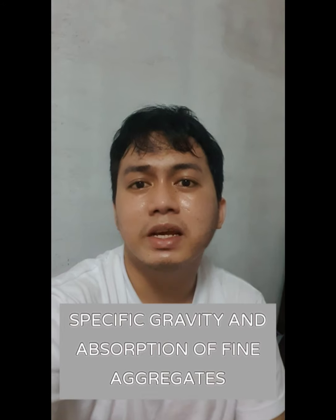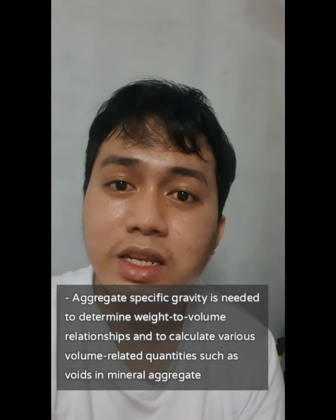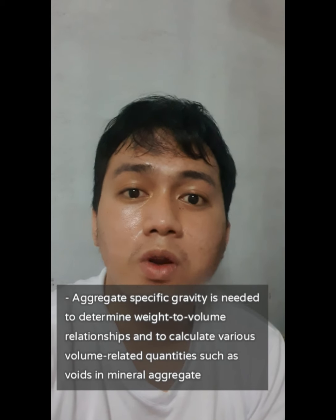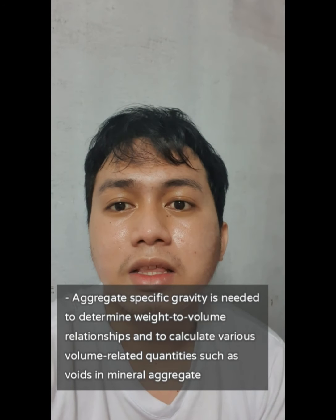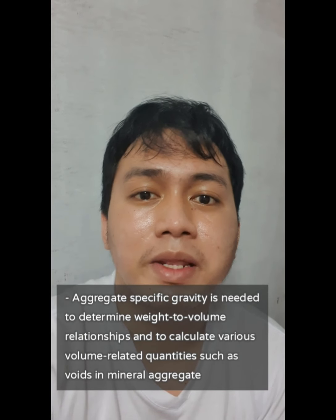Hello everyone, so today I'm gonna tackle laboratory test number 9, the specific gravity and absorption of fine aggregates. The significance and use of this method is that aggregate specific gravity is needed to determine the weight to volume relationships and to calculate various volume related quantities such as voids in mineral aggregate.